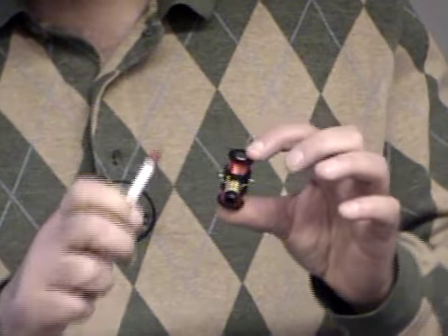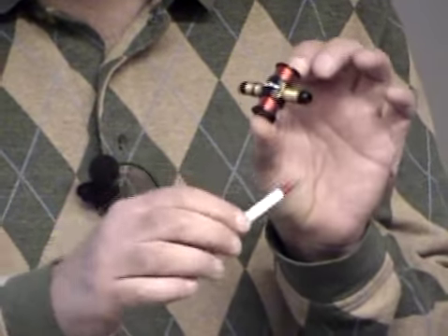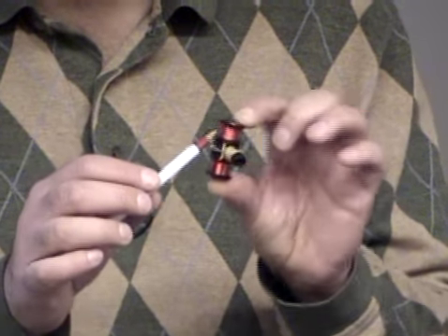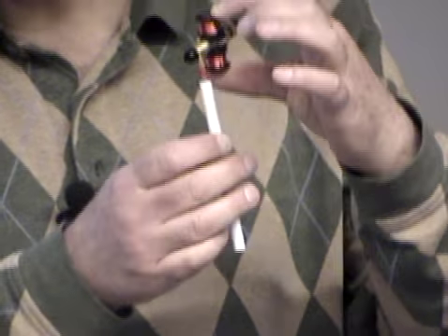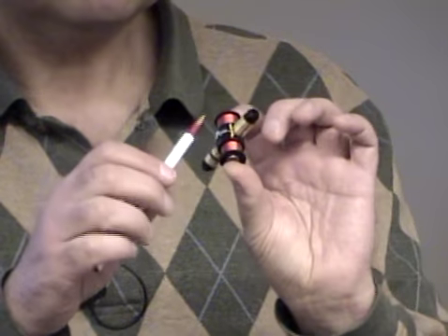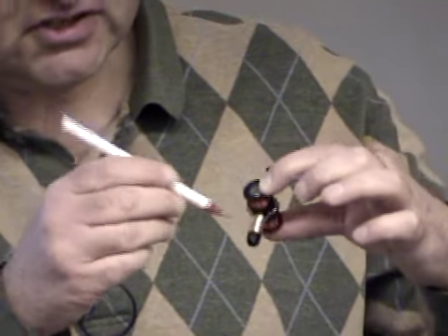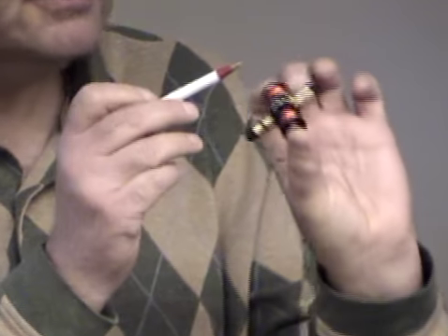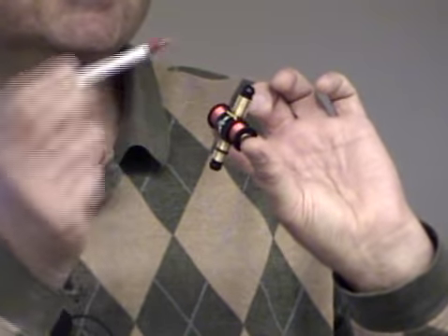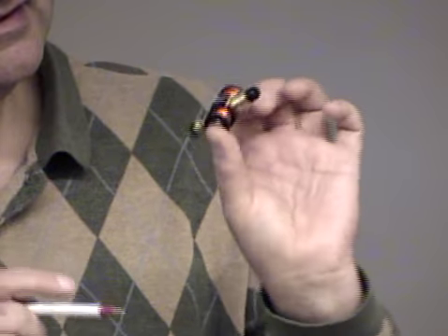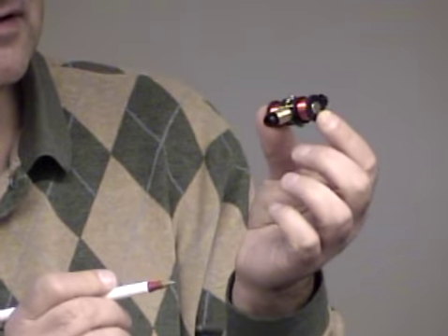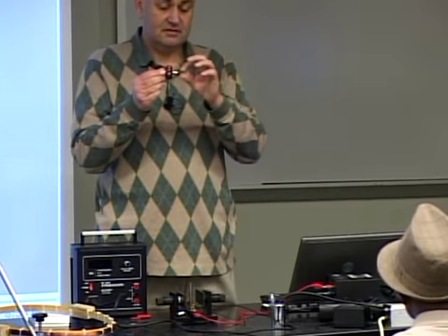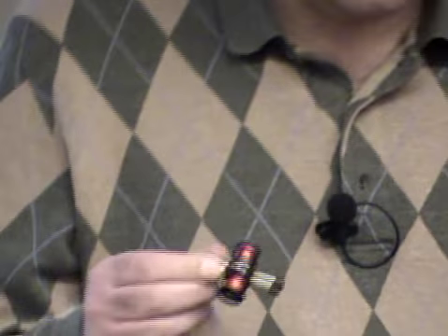One is, these loops are connected to these two pieces of metal, and they are, well, like a tube which is cut over here, on this side and on this side. So here we have two isolated pieces of a full ring, and each of those half rings is connected to that loop. This arrangement of those half rings is called a commutator.